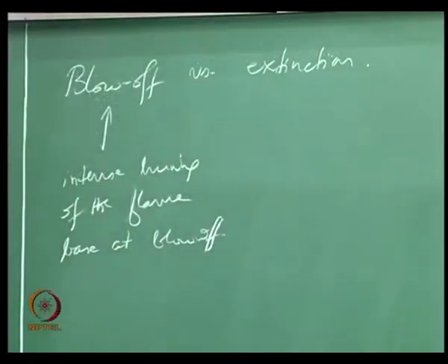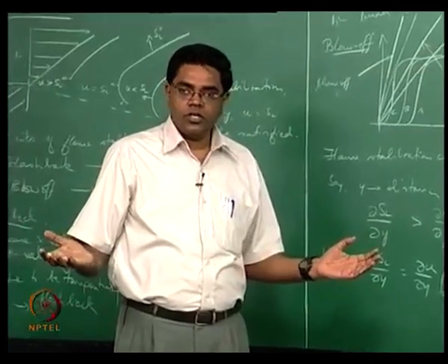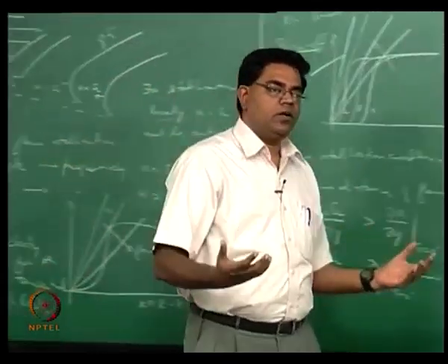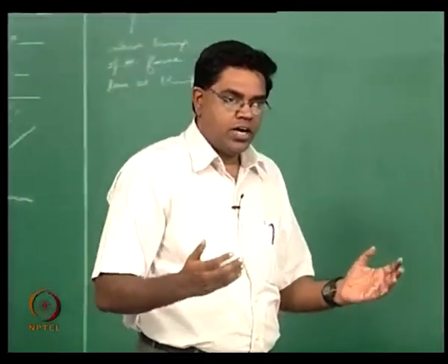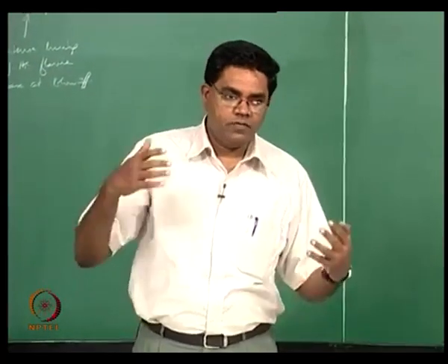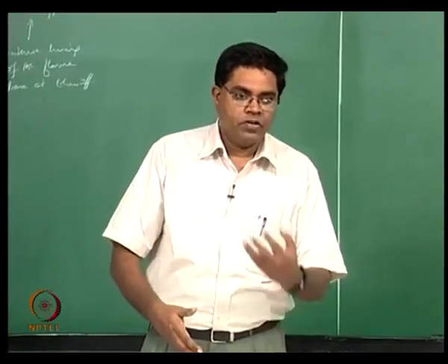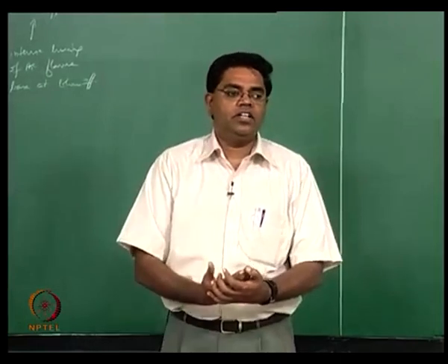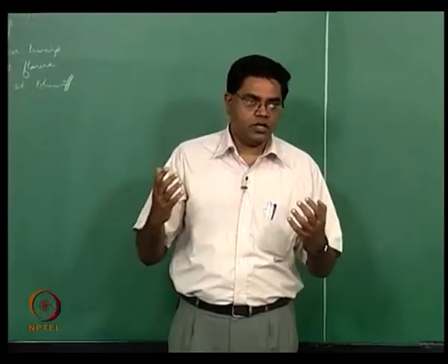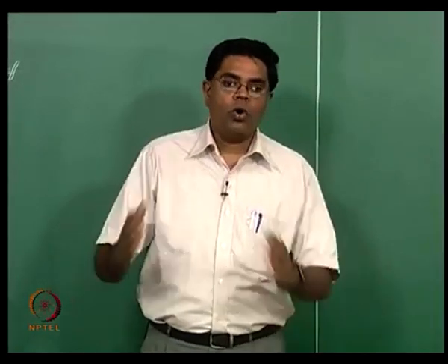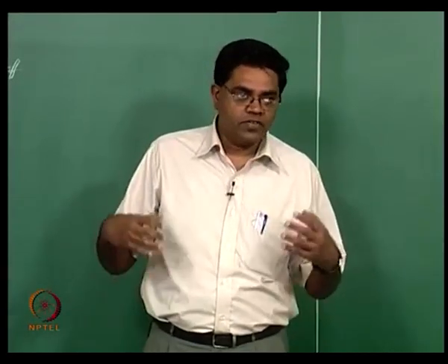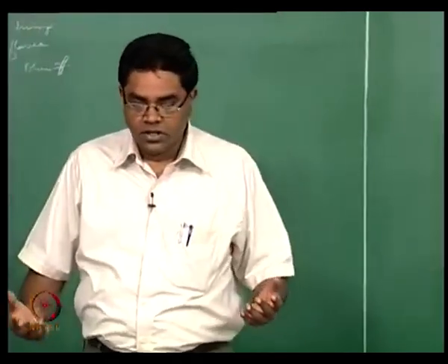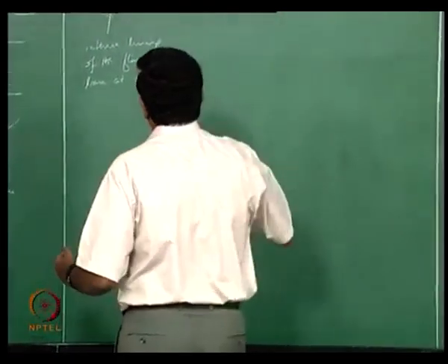Extinction is the opposite of this. Extinction is where you are progressively starving the flame of reactant mixture, right. So effectively the reactivity is coming down further and further, and since you now have a heat loss situation and a dilution situation that further decreases the SL at the flame base, so the flame base is the place where you're going to actually have the biggest hit on the intensity of burning for an extinction situation, where on the whole the flame is being starved of reactants and the reactivity is coming down, the burning intensity is coming down. It's going to actually be the worst at the flame base because of the heat loss and the dilution.